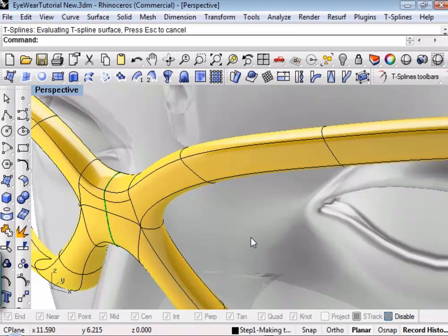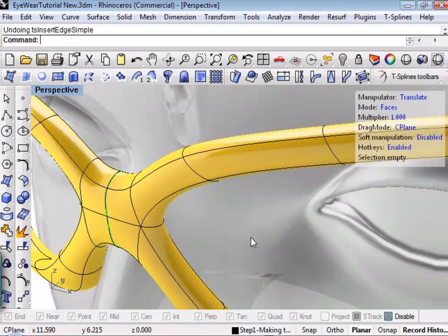There are very few instances in product design where you want something that's actually sharp, because if you zoom in on any object made on any type of modern production equipment, it's going to have a teeny tiny fillet on it. Crease doesn't give you that. Crease actually gives you a sharp knife edge.